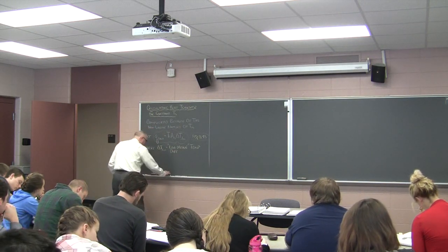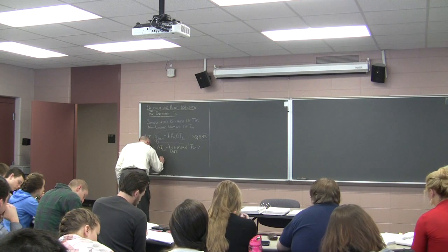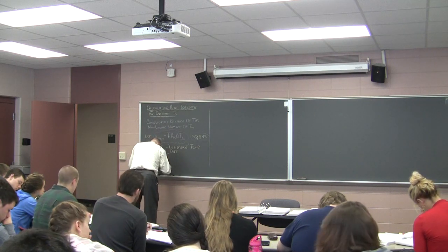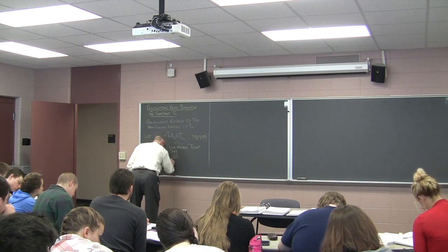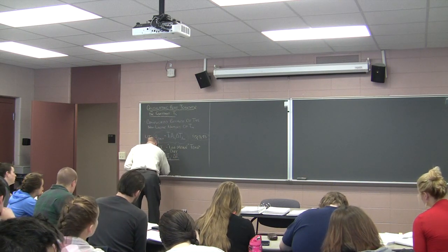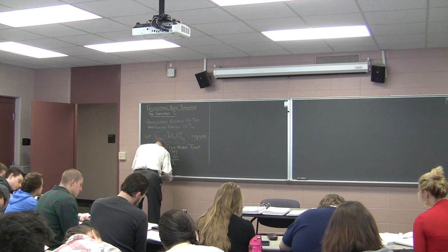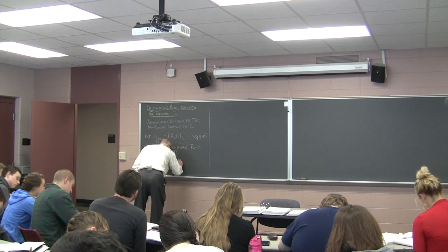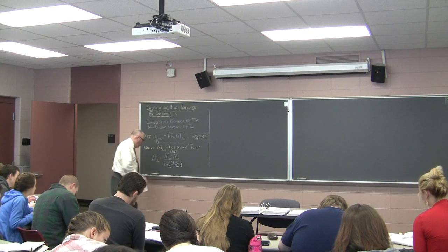And it is defined as the difference between the temperature at the outlet minus the temperature at the inlet, over the natural logarithm with an argument of the delta T at the outlet divided by the delta T at the inlet. And this is equation 8.44.